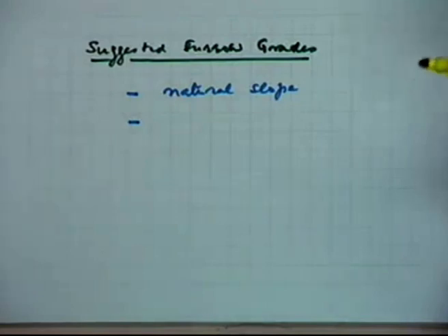In many situations, you will find that if the natural slopes are excessive, if you go in for the formation of those areas or the grading of those areas, you might turn the soil upside down. The soil which is fertile soil might be taken away and replaced with the soil which is exposed soil, which has come from the lower layers. That soil is not very fertile. So you will try to avoid that situation where the exposure of the soil might be a possibility if the grades are very excessive.